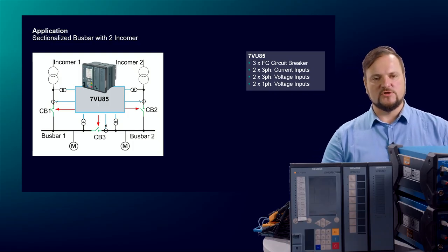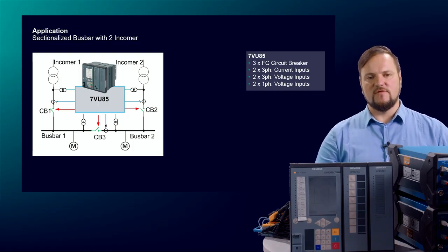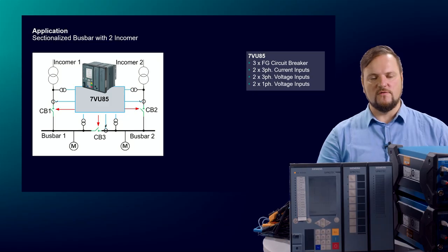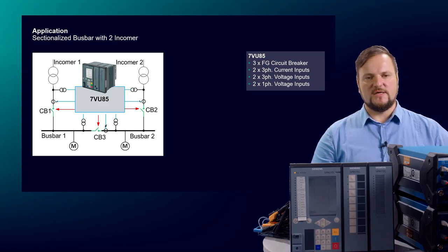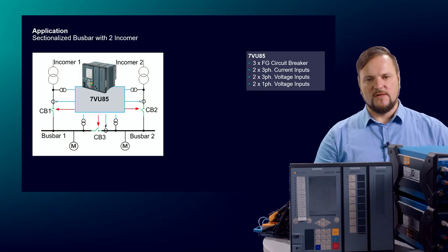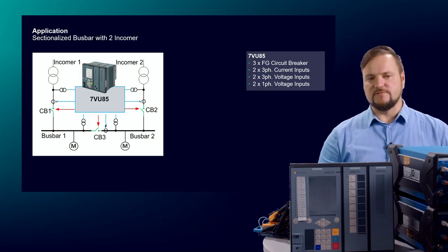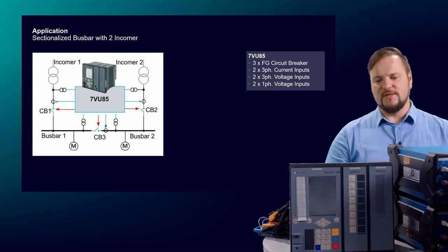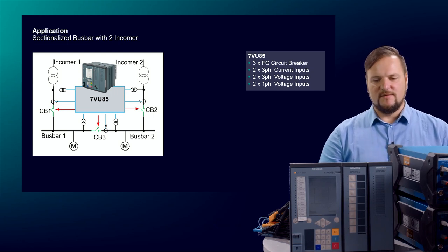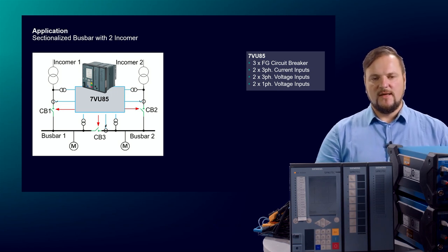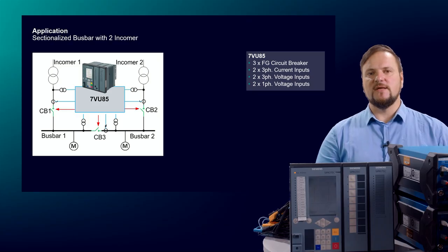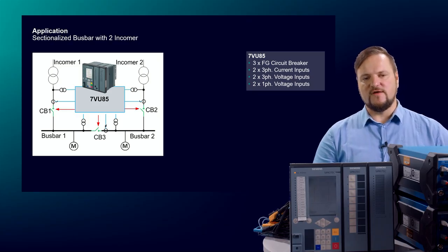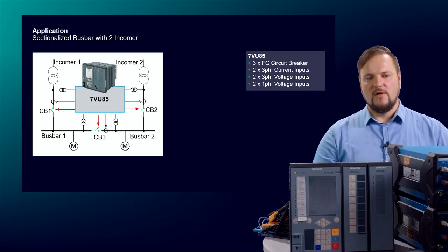Now with the next version, with the 9.70, we also support the single-phase connection type for the motor bus, for the busbar, instead of a 3-phase voltage input. This of course reduces the necessary hardware a little bit, and especially for retrofit applications, we will always have phase-to-phase voltage measurement on the motor bus.